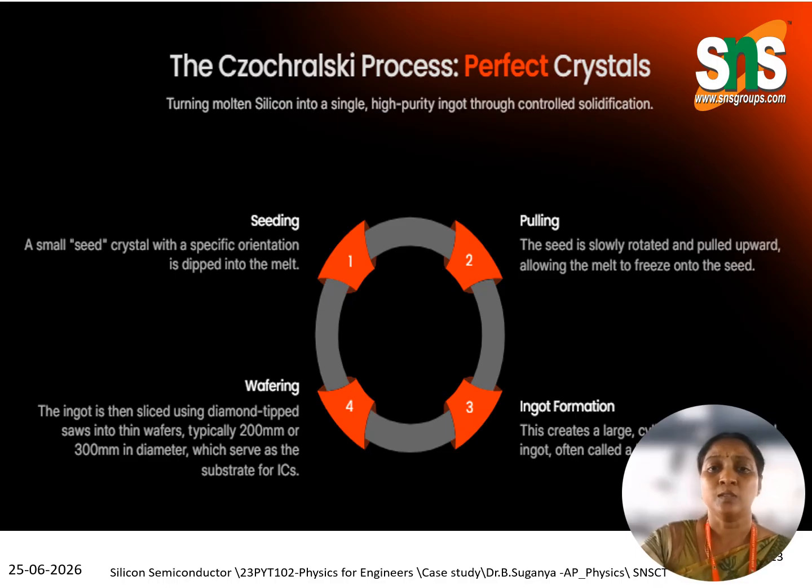Czochralski process. So how can we grow a perfect crystal? The first step is seeding the crystal. A small seed crystal with a specific orientation is dipped into the melt. The second process is called pulling. The seed is slowly rotated and pulled upward, allowing the melt to freeze onto the seed.